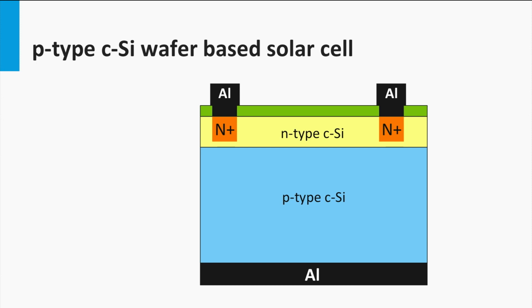At the back surface of the solar cell, we have similar issues playing a role. As the electrons have to be collected in the N-type layer, the holes are collected at the back contact. As electrons are the only charge carriers that exist in a metal, you have to realize that the holes recombine with the electrons at the contact interface. If the distance between the PN interface and the back contact is smaller than the typical diffusion length of the minority electrons, the minority electrons can be lost at the defects at the back contact interface due to Shockley-Read-Hall recombination. How can we reduce this loss mechanism?